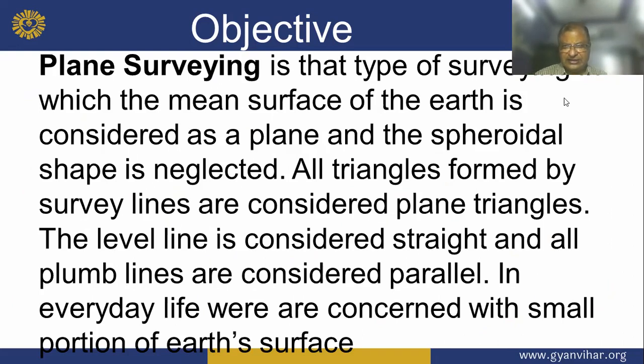All triangles from the survey lines are considered plane triangles, the level lines are considered straight, and all plumb lines are considered parallel.